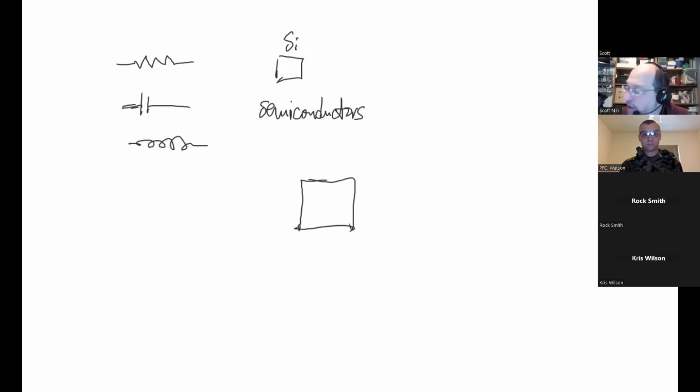However, what's cool about silicon is that we can actually take silicon and inject, as we're making it, a little bit of boron or phosphorus or arsenic or any number of different things that have a couple of extra electrons, or they are lacking a few electrons. And by doing that, we can give it a few extra electrons. And if it has extra electrons, it becomes slightly negative because electrons are negative. We could also throw some stuff in there that has a few extra what's called holes. A hole is a missing electron, and that would give it a slightly positive charge.